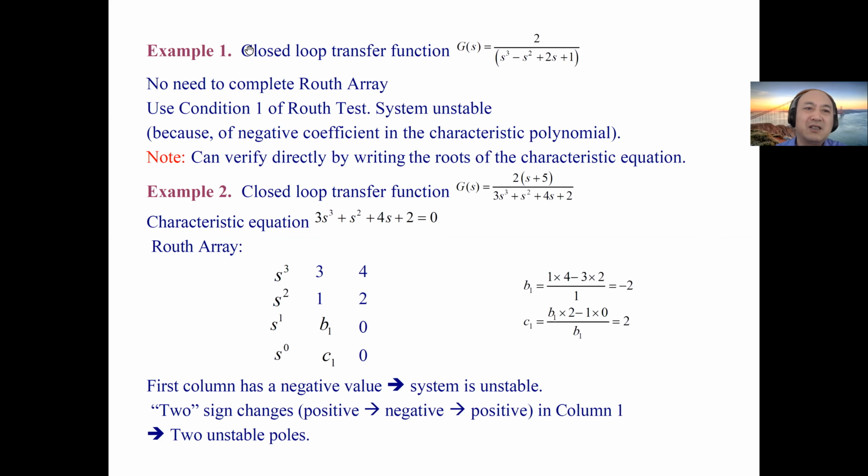So you got a closed loop transfer function. Remember, the closed loop transfer function is usually like a controller C, a plant G, over 1 plus CG. Given C, given G, you get this. But we usually use the symbol T. T is the closed loop transfer function.